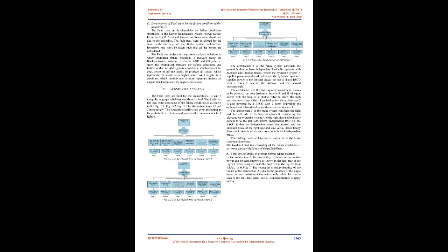The uncommanded emergency braking less than commanded is caused when the crew wants to apply the brakes during a phase such as landing, but the brakes applied are less than anticipated, which may be due to the malfunction of the LRUs, or error in signals sent from the pilot pedal to the signals sent from the BSCU to the mechanical items such as the brake control valve and shutoff valve.